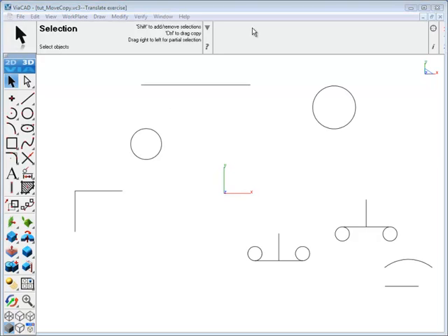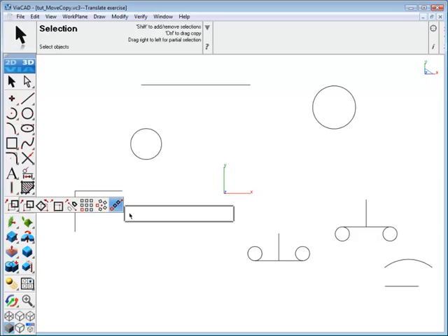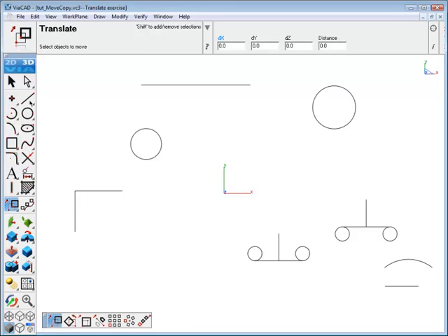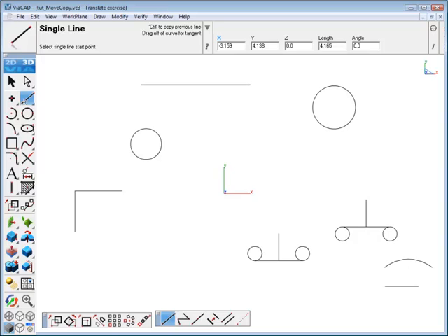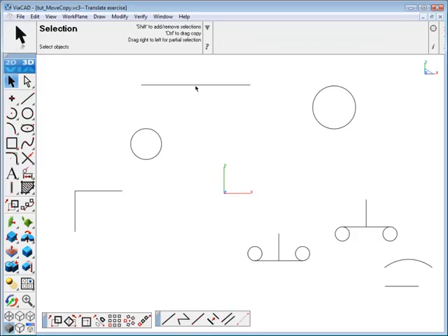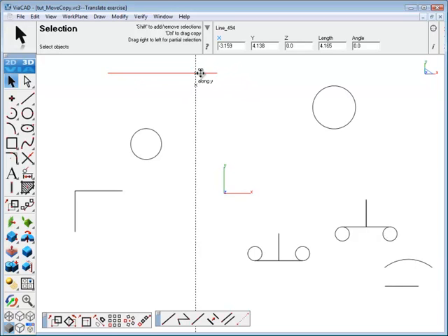To begin, we'll drag off the tool sets that we need to complete the tutorial. To move a selection, it's quite easy. Position your cursor on the selection, press the mouse button and drag to a new location. Position the cursor using snaps for precise drag and drop. Watch the prompts. It says hold the control key down while you drag to make a copy.